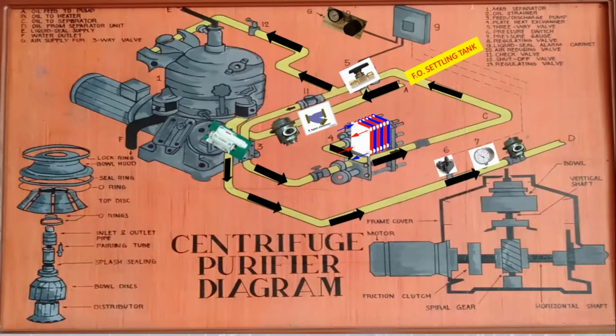Finally, the fuel oil will be supplied to the fuel oil service tank, where the contents are settled and evaporated, and sediments and water contents drain to the fuel oil drain tank. In such a way, the clean and purified fuel oil from the fuel oil service tank will be used for the main engine, auxiliary engine, auxiliary boiler, and waste oil incinerator.